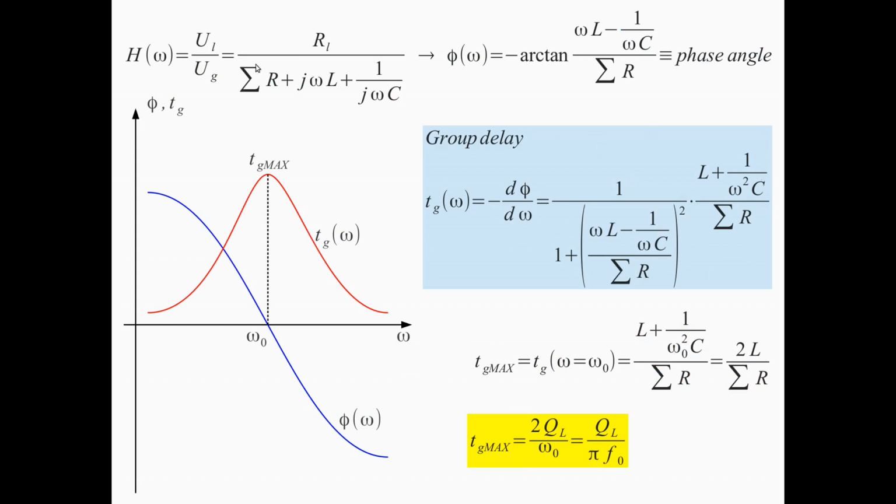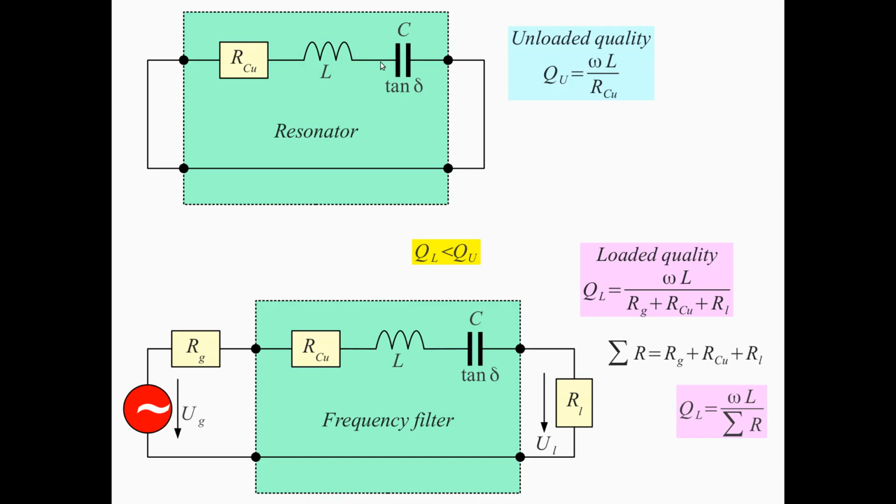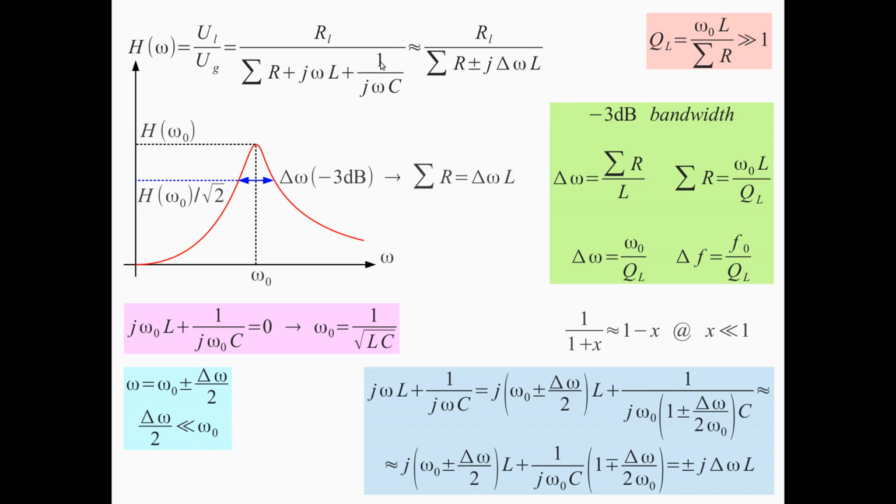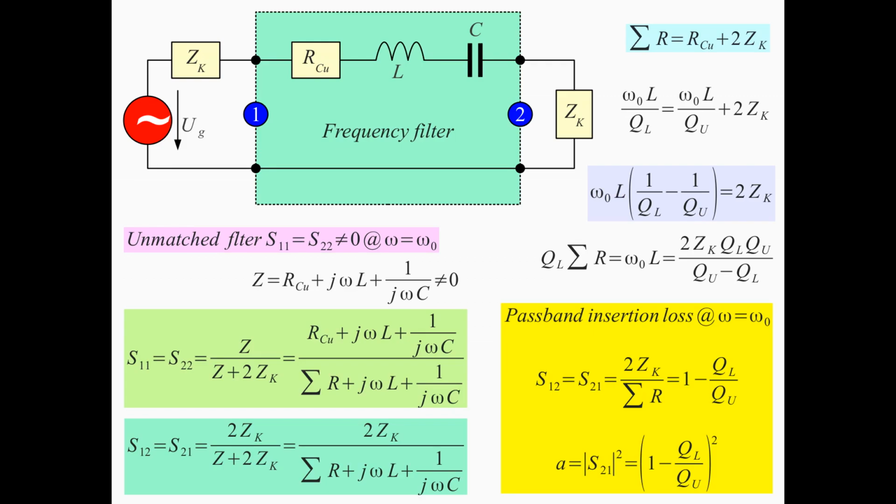The expression for the group delay comes from the phase angle of my filter response, and the phase angle comes out of the transfer function of my filter. Transfer function as we had it written here. If we were using S parameters like here, it is further 1/2 of this, because we are just taking this voltage in place of this voltage.